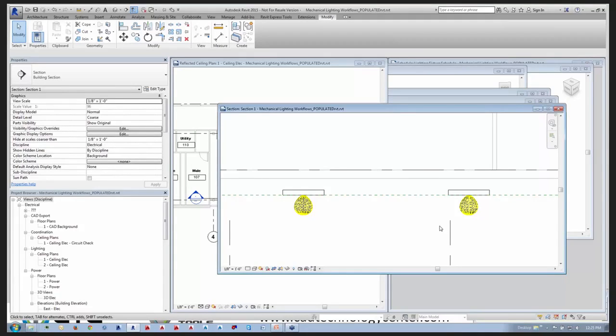And further, I wanted to point out that because these clearance boxes are 3D modeled extrusions, you'll be able to run clash against them, whether you're doing your clash in Navisworks or right inside of Revit.